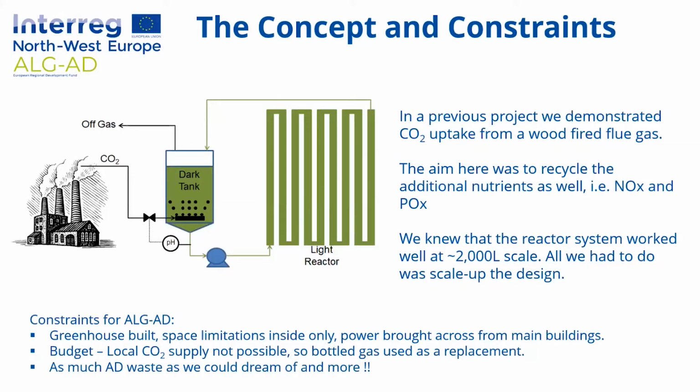So it basically is a batch reactor in essence that recirculates. But obviously with time, we could take materials out of the system and put fresh materials in, so it becomes a pseudo continuous reactor. Now, how we normally control the system, one of the major parameters is pH, and we control that by injecting carbon dioxide into the system, forms carbonic acid, and therefore lowers the pH. So as the algae grow, they consume the carbon in the system, and therefore the pH rises.